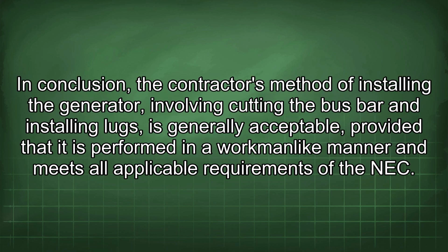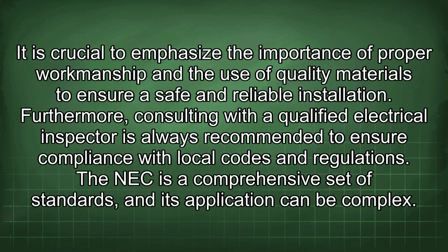In conclusion, the contractor's method of installing the generator, involving cutting the bus bar and installing lugs, is generally acceptable, provided that it is performed in a workmanlike manner and meets all applicable requirements of the NEC. It is crucial to emphasize the importance of proper workmanship and the use of quality materials to ensure a safe and reliable installation. Furthermore, consulting with a qualified electrical inspector is always recommended to ensure compliance with local codes and